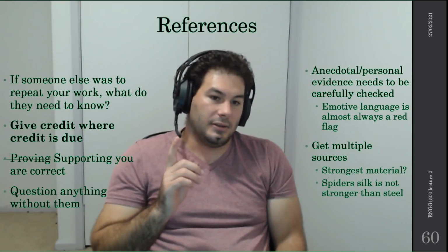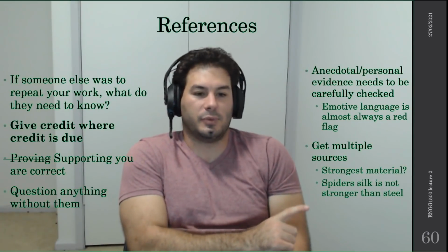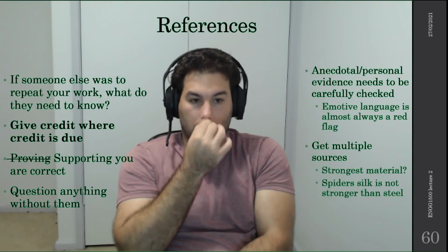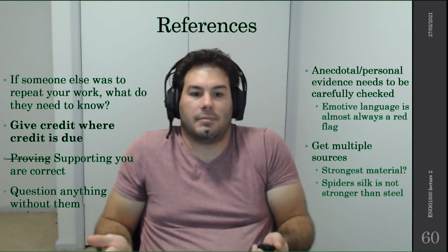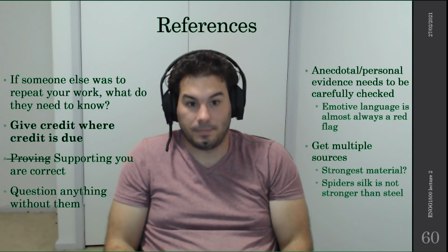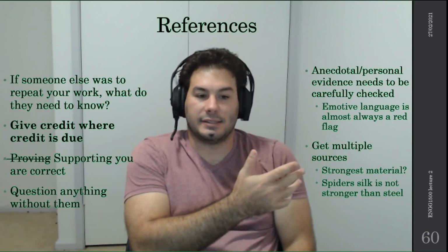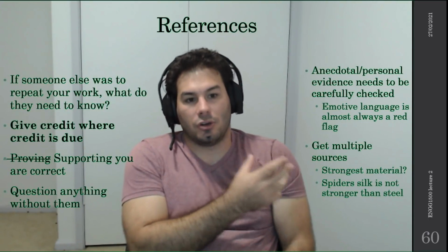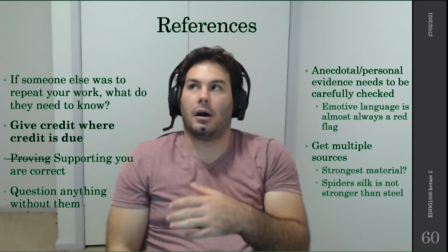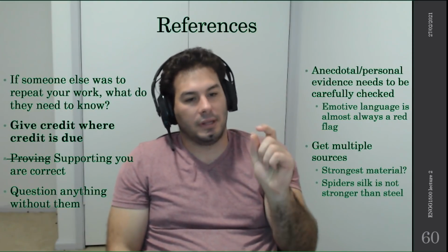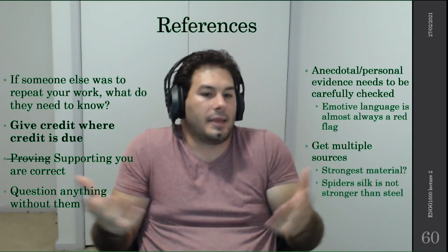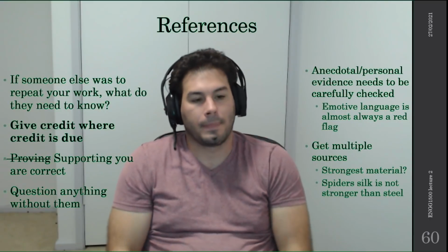And also, what does stronger mean? Because when they do the spider silk test, it's a single strand perfectly in tension. Well, that's not what stronger means to me. I want to be able to put it in compression as well. Spider silk is useless in compression. So this is a bad selection of data that leads people to believe things that are only true in unbelievably specific circumstances, and then they apply that knowledge to everything, and then they are very wrong most of the time.